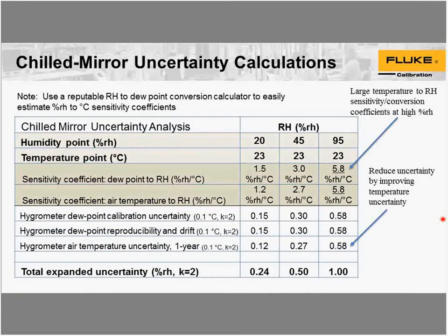At 15% RH, what do you use to increase and maintain humidity in your cal lab? We have two main approaches. We actually have one room where we're currently using a portable humidity generator because it's particularly dry with the cold weather we've been having recently. But really it's an in-duct system that we're using in our laboratory. It uses steam, heated water, to humidify the room.